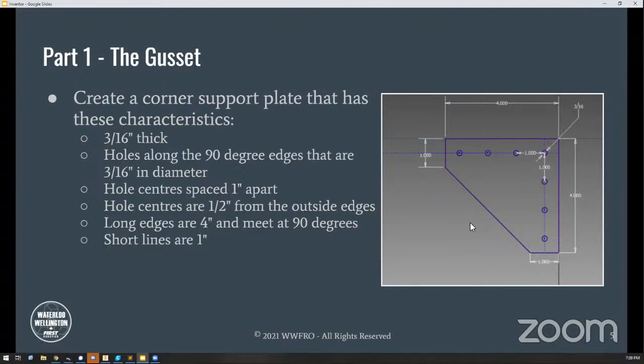And if you can put another gusset on the other side of it. So these 2 plates sandwich in 1-inch square tubing to make a structured corner. The size of the rivets that we end up using require a 3/16 hole. So that's why those smaller holes are measured out to be 3/16.